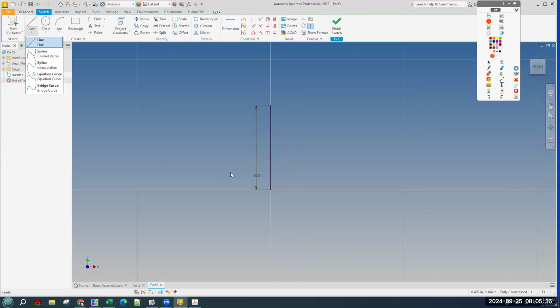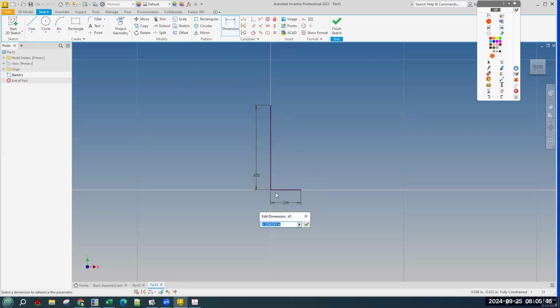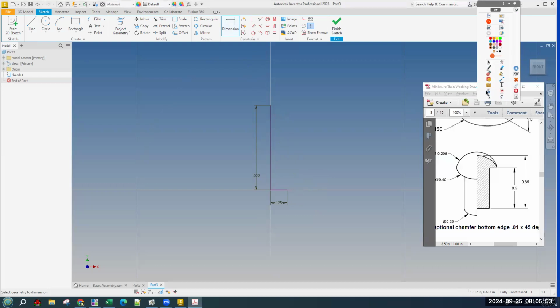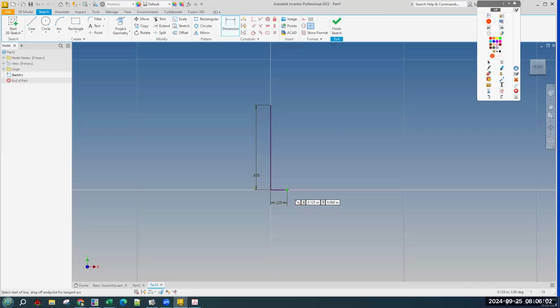But either way, a line across the bottom. And dimension this 0.25/2 or 0.125. All right, then we're going to work our way around. We've got this, we've got this. We just need a vertical line that's 0.5. So a line from here straight up. And before I click to set it, as long as it's snapped to vertical, I can just type 0.5 and it'll make that line.